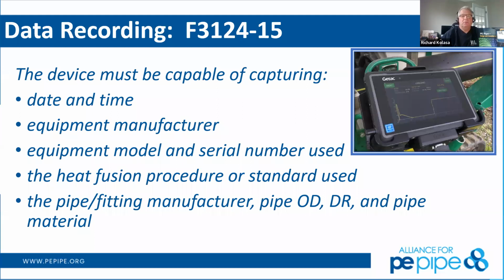Yeah, and this is really important because when we typically produce a string for polyethylene, we do it above ground. So the whole string is done above ground, and then we may relocate that string to somewhere else. So you can actually walk along the pipeline if you put it in the trench and mark those specific joints right at that point. And it's a wonderful thing to have. Then you're not guessing where a potential issue may occur or may not occur. Usually it's not, but it's very precise. And I think it's just a fabulous tool. Yeah, and it's a real time saver for the field, and then for your data house on the back end.